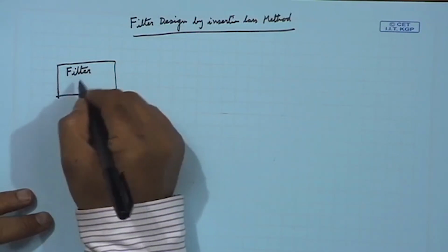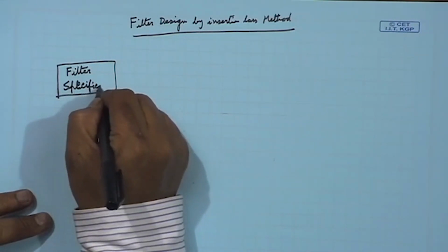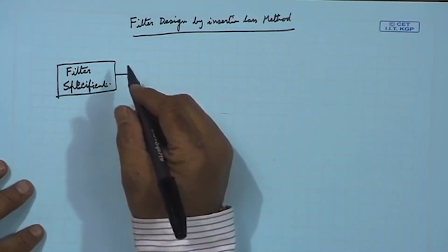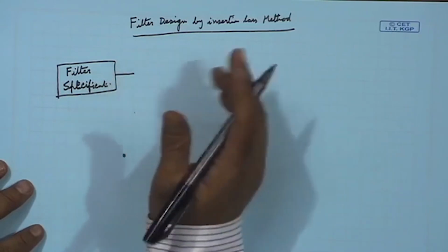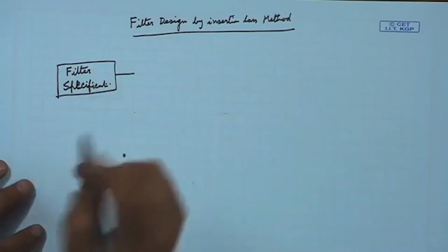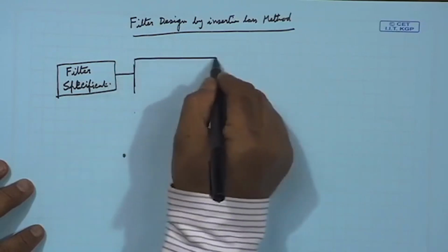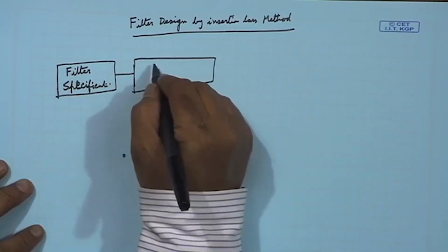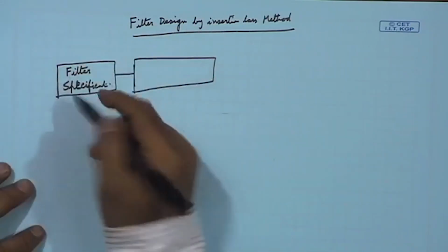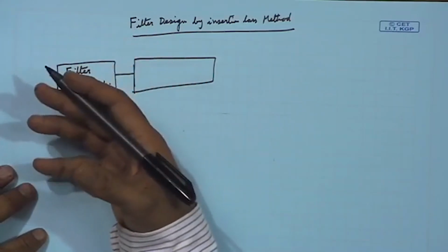So, I am now giving you the whole process flow. First, from the filter specification you need to understand what the PLR or insertion loss requirement will be, and what type of filter I will use, which we have already seen. Once we have that, we do it. This is an important step. Whatever the filter may be, band pass, high pass, band stop, or low pass,